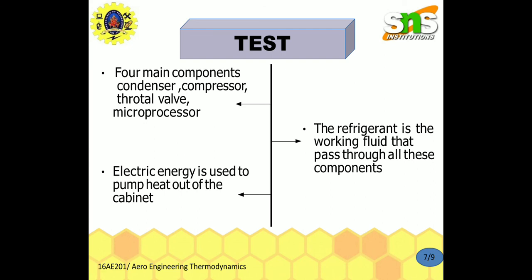The air cycle machine is very common, however, on gas turbine powered jet aircraft, since compressed air is readily available from the engines' compressor sections. These jet aircraft's cooling and ventilation units also serve the purpose of heating and pressurizing the aircraft cabin. This is how the refrigerant works, and the efficiency and performance will be given in the upcoming discussion.